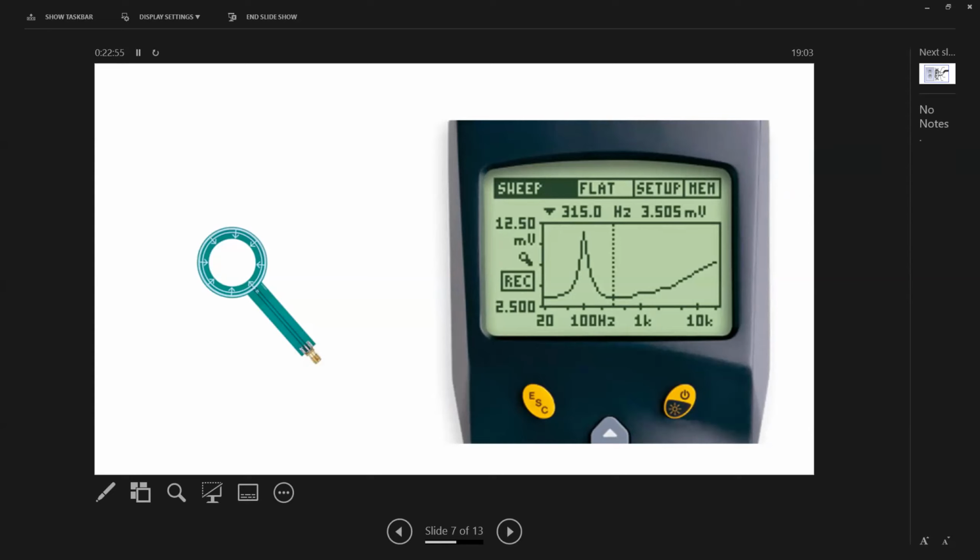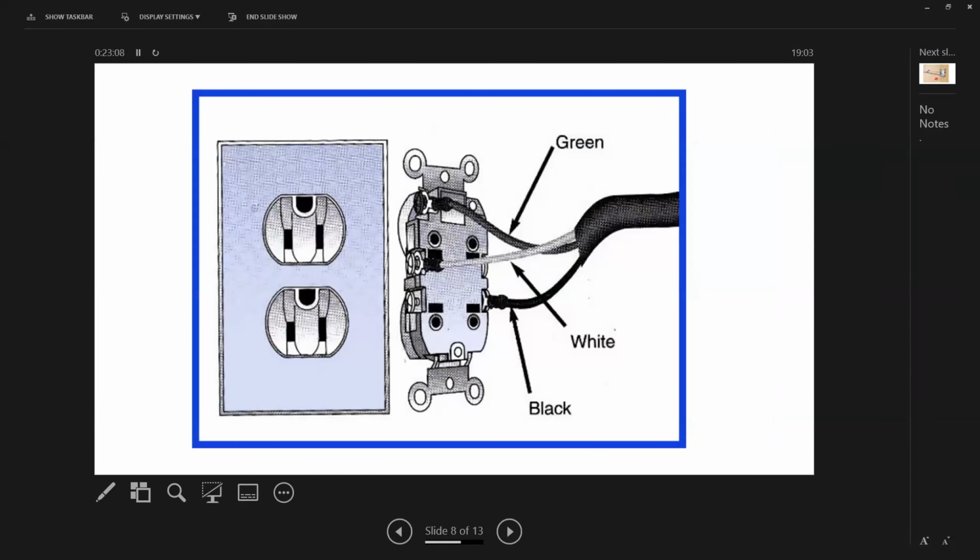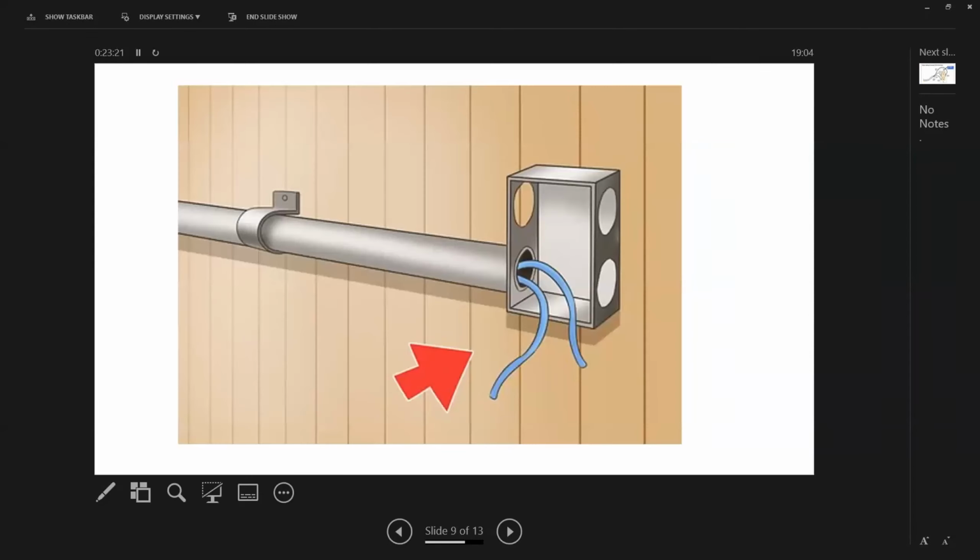So again, talking to the plant electricians, I asked them, how is this done? Is there Romex inside that conduit? They assured me, yup, there is. So the way the socket would be wired is the green wire would be going to a safety ground, and the white and the black wires would be going to the terminals, just like always. Not a problem. Everything should be fine. And that's what they said was there. Okay, I trust you.